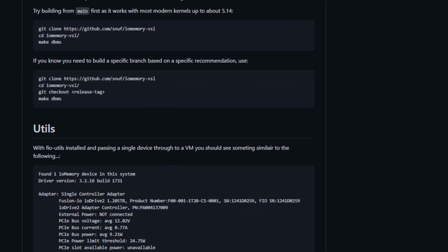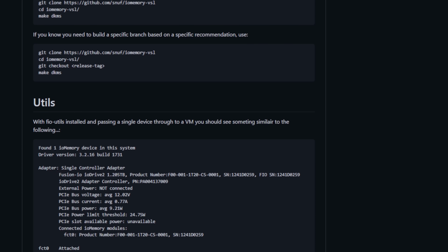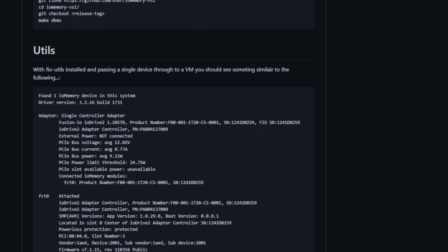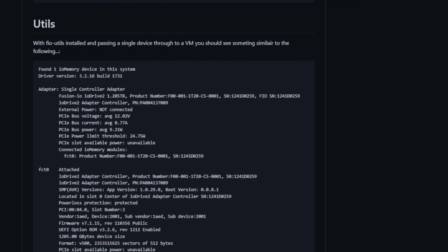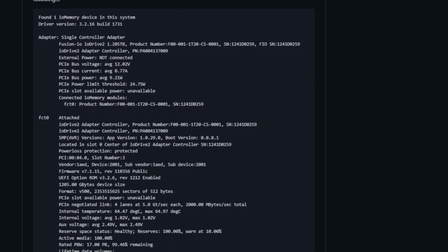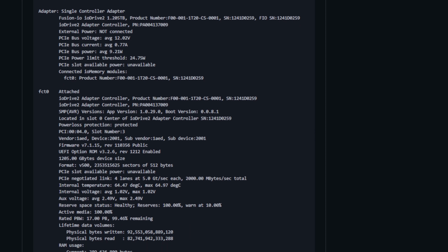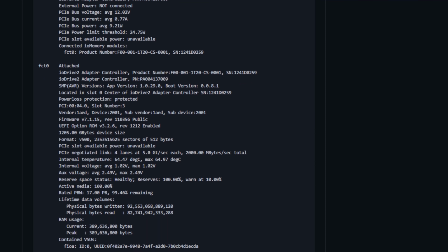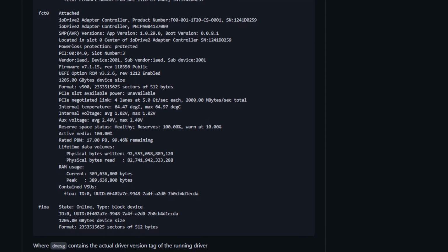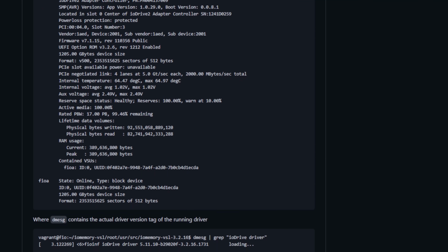The first thing that happens with these, because again, it predates NVMe, is it requires a special driver, and the special driver is not entirely open source. It's a little bit open source, but there's a binary blob inside the source. In normal operation with these cards, when you try to use them, the driver loads and initializes the card, which bootstraps the processor on this card, which then reads from the flash, gets an idea for how the card is laid out, and then everything starts up and you're running.